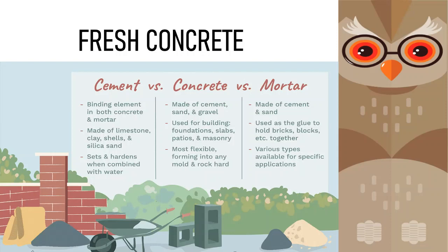And what about mortar? Mortar is used to hold building material such as brick or stone together. It is composed of a thick mixture of water, sand, and cement. The water is used to hydrate the cement and hold the mix together. The water to cement ratio is higher in mortar than in concrete in order to form its bonding element. So when mixed, it is a much thicker substance than concrete, making it ideal as a glue for building materials like brick.